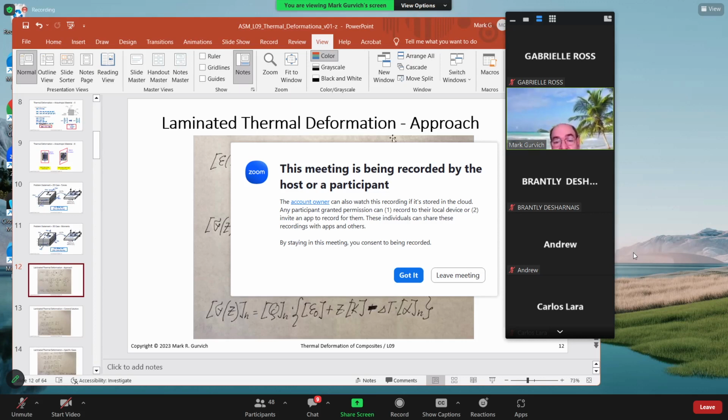But now we're adding an extra component of thermal expansion. So we have delta T multiplied by this vector of alpha sub X, alpha sub Y, alpha sub XY. And again, here I had to use XX, YY, so for this reason I'll probably clean it. Sometimes it's used in tensor form, sometimes in matrix form. Here, I did not use tensor form for simplicity, but you know how to define it.